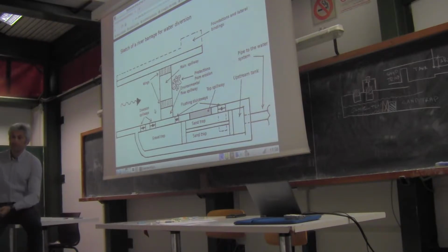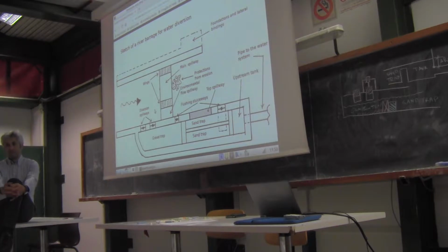I have just a question. So these structures are built and then verified for the flood? Yes. Or is there a process through which you can take into account the flood while you are designing? No, typically what you do is you base your design on the design variables related to water resources management, and then you verify against the flood flow.